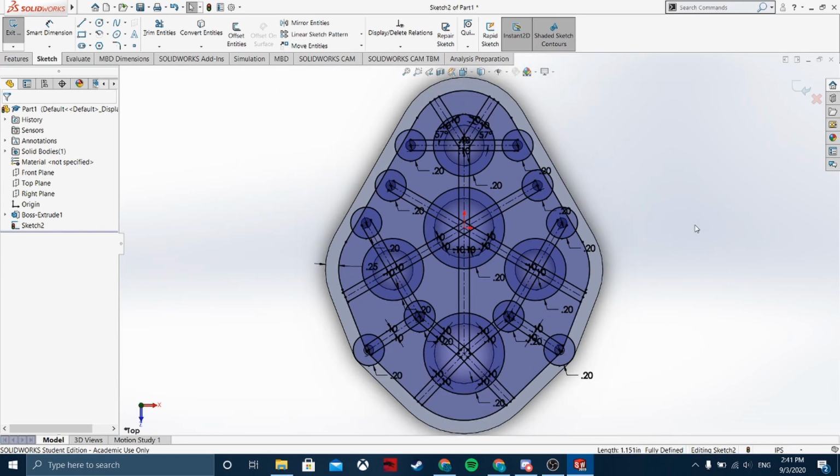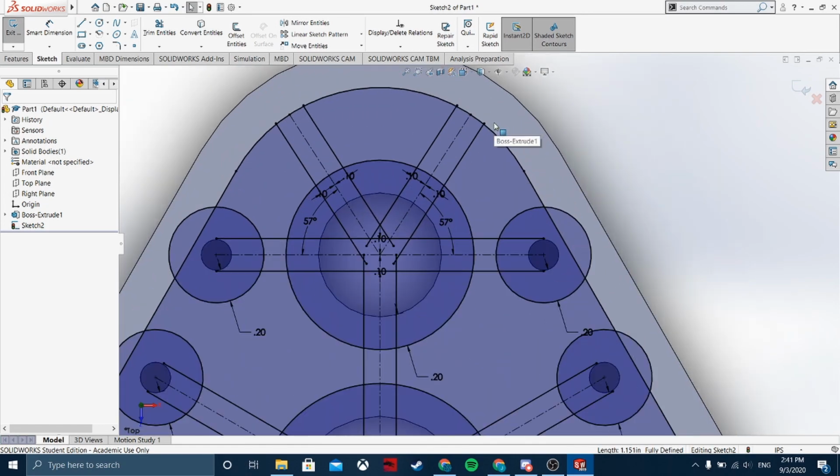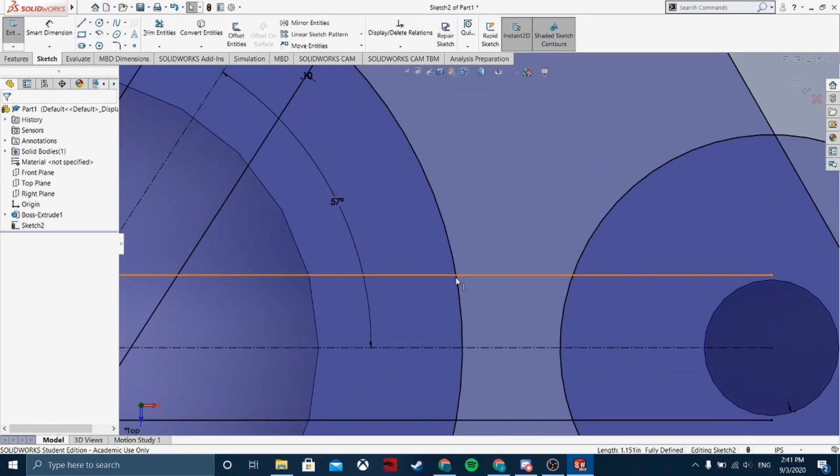So we gotta fillet these somehow, because the CNC is gonna be a drill, and so the drill can't CNC super sharp edges, right? So we gotta fillet these, and we could just use the fillet command, but for some of these, using the fillet command wouldn't work because, say, look at this corner and this corner over here.